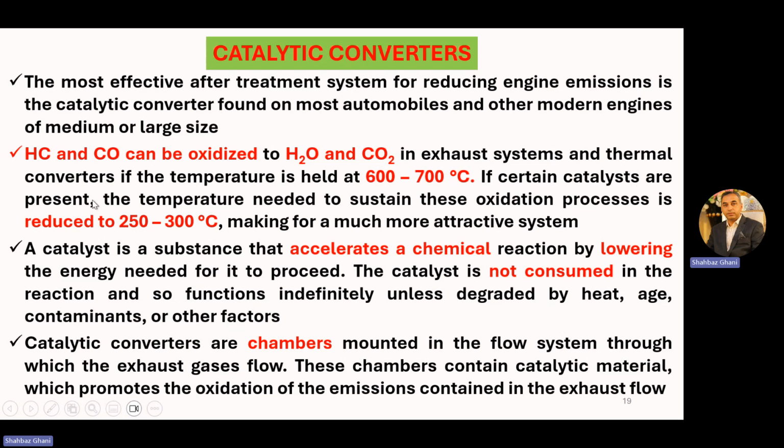If certain catalysts are present, the temperature needed to sustain this oxidation process is reduced to 250 to 300 degrees Celsius. So we are using some catalyst, and with the help of that catalyst, we are reducing the temperature for this oxidation process to 250 to 300 degrees Celsius as compared to 600 to 700 degrees Celsius, making for a much more attractive system.